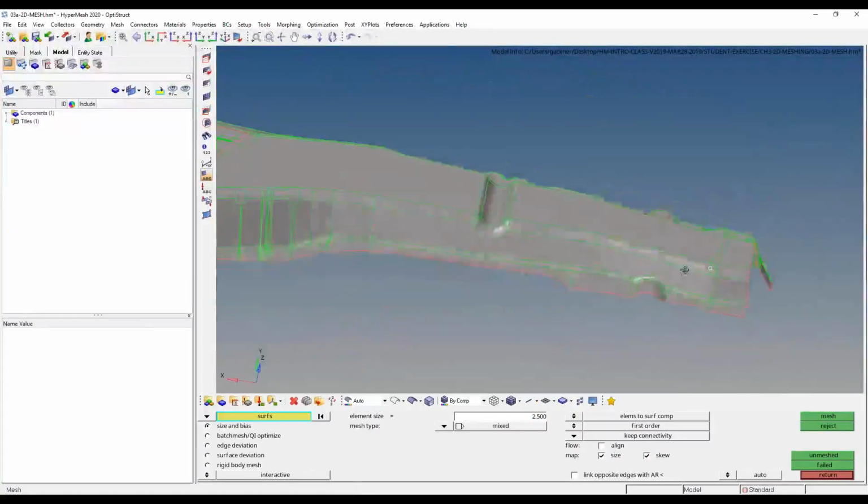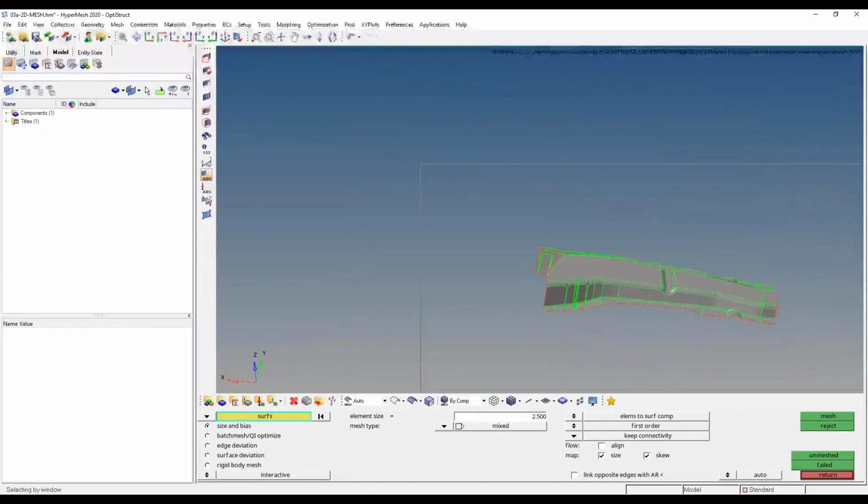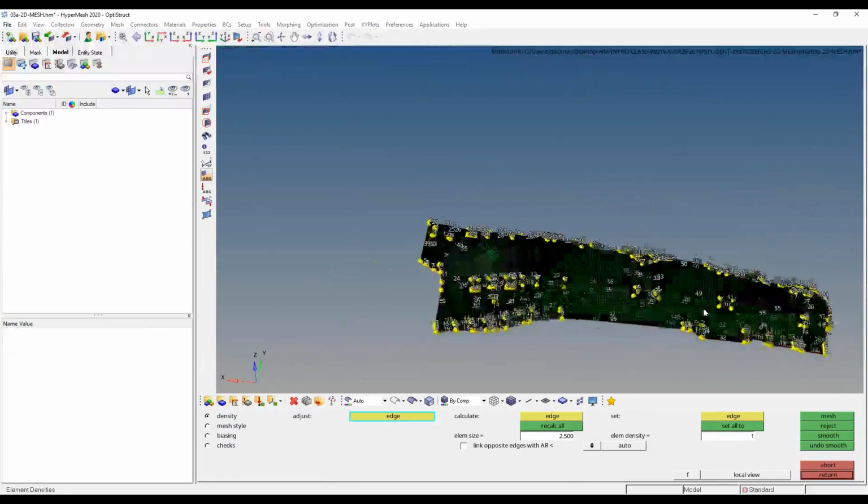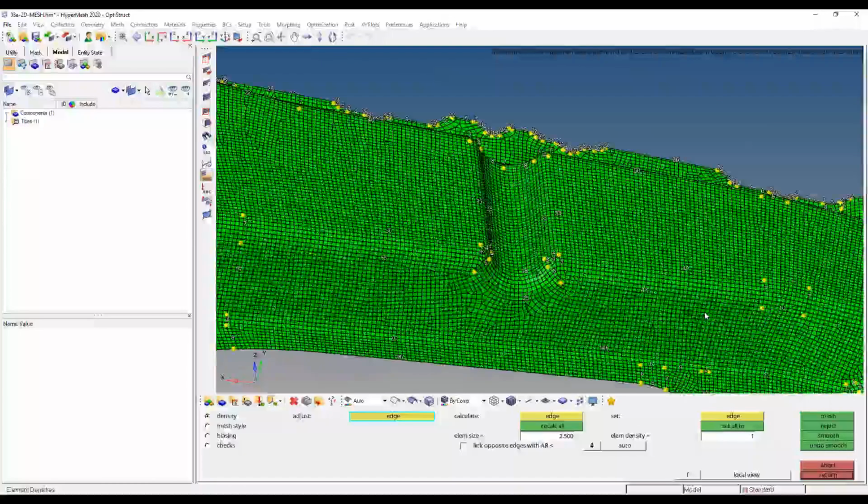And while I'm doing my meshing itself here, I would never recommend, especially for parts that you're really concerned with, just grabbing all of the surfaces and meshing them in one shot. It'll work. There's a lot of logic built into HyperMesh. It's not going to give you terrible results, but I really think you're doing both yourself and the product a disservice by just grabbing everything and throwing a quick mesh on there. Yes, it'll work. It won't be terrible, but there could have been some other things along the way that we could have probably improved.